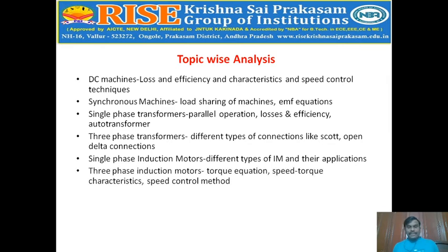Okay, then the three-phase induction motor. What is the torque equation, how to find the efficiency, what are the characteristics. It operates in generator mode, in motor mode, and in braking mode, that is the plugging mode. What techniques are used with the three-phase induction motor? Combination questions come in the induction motor, and the V/f control method is used for speed control of the induction motor.